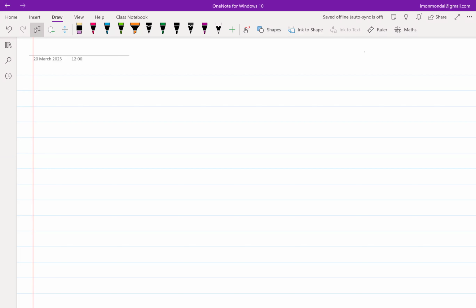If it becomes a significant portion of the time period of the signal, and you are not careful and you open up one port or short one port, it is quite possible that because of the reflection, the actual device might not be seeing an open circuit or a short circuit. It might be a combination of both. Even worse, if it's a high power device, due to the reflection there can be a lot of signal swing, which can break the circuit, or there can be